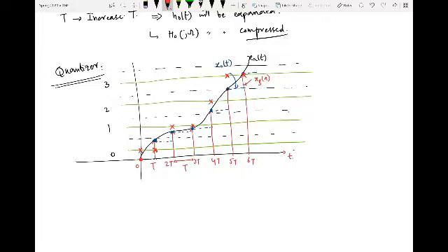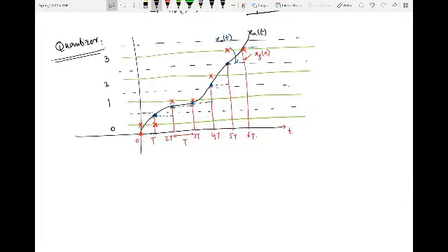So in terms of values, first of all we write the actual sampled values. We also scale the voltage level here. You see this is 0, 1, 2, 3 and 4. So the center lines are 0.5, 1.5, 2.5 and 3.5. The actual first sample has the value of, let's say, 0.9. The next one has approximately the value of 1.3.